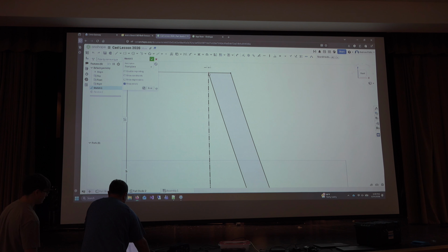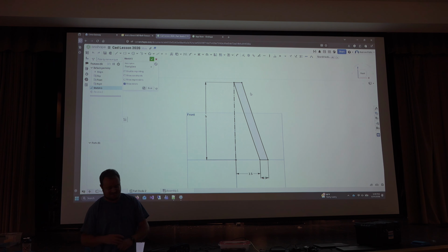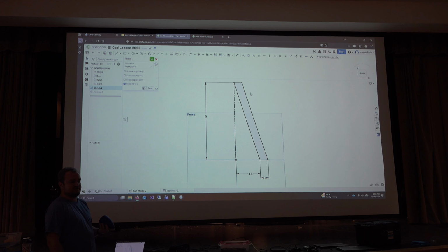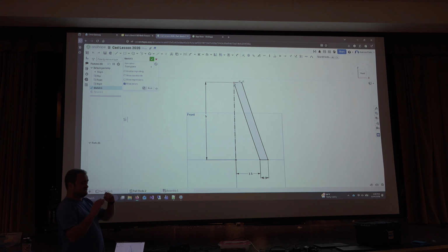Okay, so we're going to need to change the sketch because apparently OnShape doesn't like it when you revolve around a point that's part of the shape. So what we're going to do is change it a bit so that just like this one, it's got a hole in the middle of the cone. Because then hopefully it won't yell at me anymore. So in order to keep this simple, I'm going to come back up to this top point because I want to now take the top of the cone and move it over.